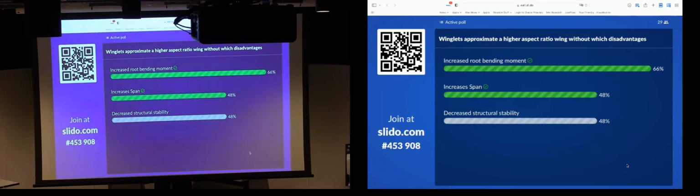So when I started working for Delta Airlines 26 years ago, we had several 727s that we had retrofitted with winglets. And it turns out that for our typical mission at the time, those aircraft burned more fuel than the ones we didn't retrofit. The reason is Delta at the time flew 727s from Atlanta to Macon, Georgia, a grand total of 60 miles, so 100 kilometers.